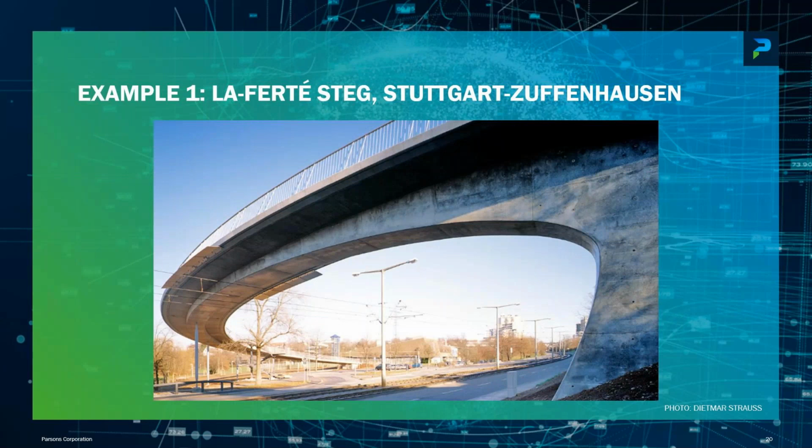Here you see the situation with the large abutment and with this column. It is protected with a vehicle impact protection structure. But if a major truck comes that aims straight for the bridge, I don't believe that this device will help you to protect the column, but the bridge will stay up, and that's important. And this you couldn't do with a bridge that is on bearings. But with an integral bridge where the superstructure is framed in, it's held back, and where the negative moment capacity is provided, you can do this. And that way you create better structures.